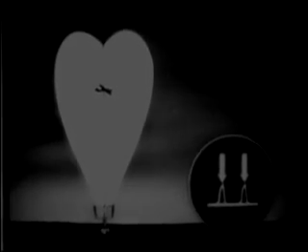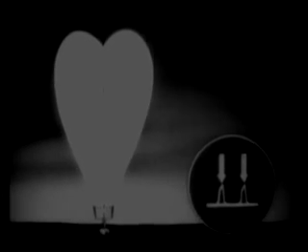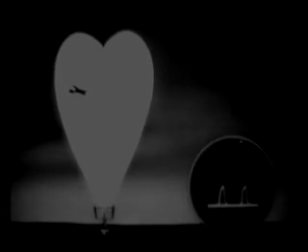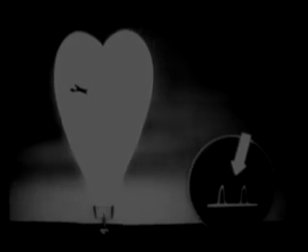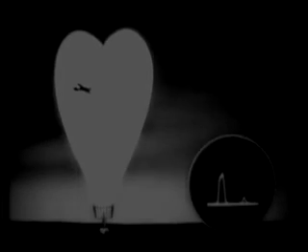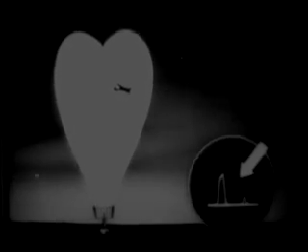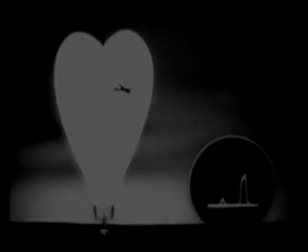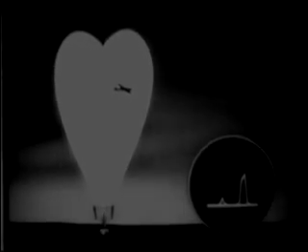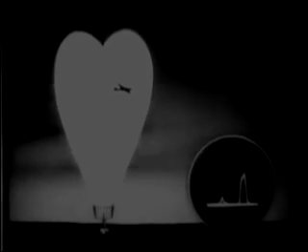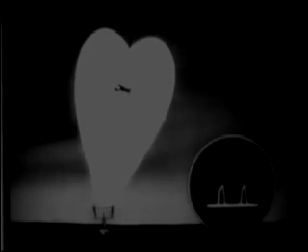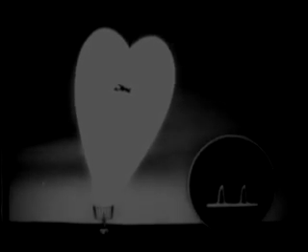But if the target gets off-center, naturally it's going to be in a stronger part of one lobe and a weaker part of the other. Here, for instance, the target's moved to the left, so the left pip gets bigger, the right one smaller. If the target moves to the right, the right pip gets larger. To center the target, all you have to do is traverse the antenna toward the larger pip until the two pips are again balanced. Then you know the target is centered in your beam and you're exactly on target. Keep the pips balanced and you'll stay on target.